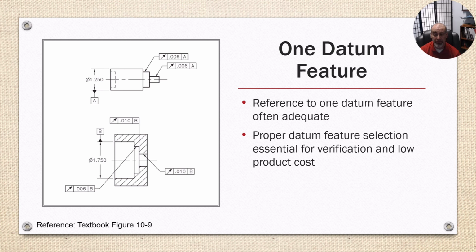I've worked recently with a local manufacturer that's struggling to make a part because they call the runout to a face that has a loose tolerance on it as opposed to the center axis of the part. And so they're having to hold this 90-degree face to a super tight tolerance in order to control the runout.